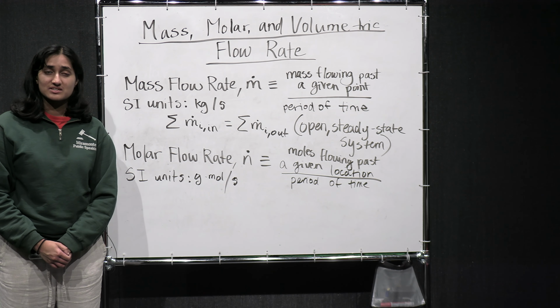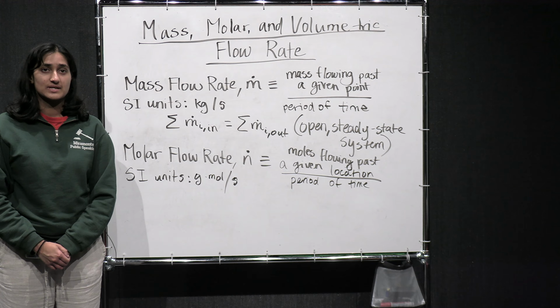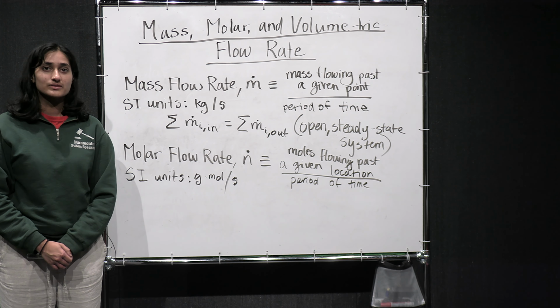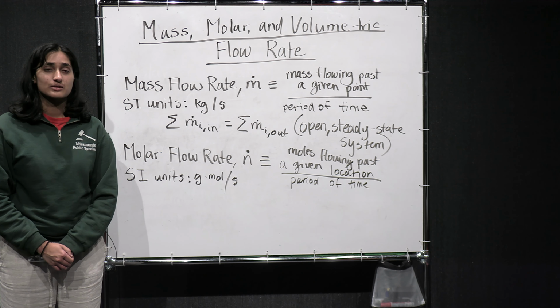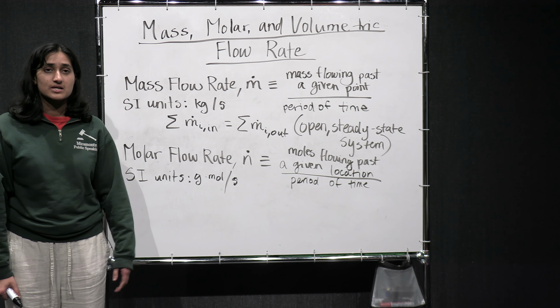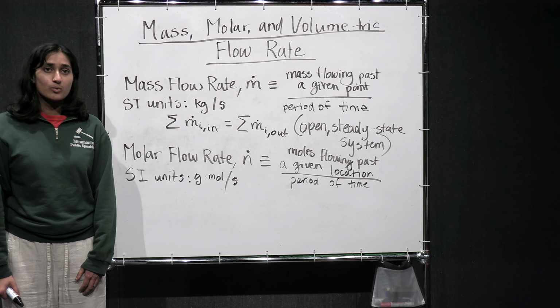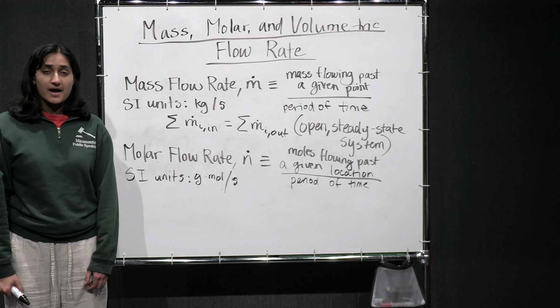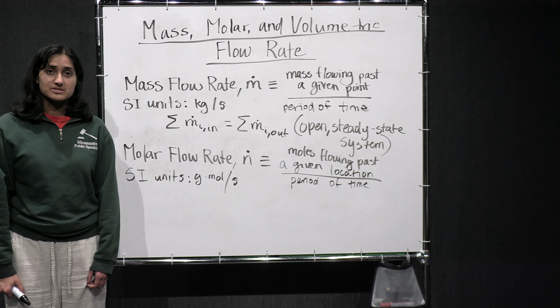For reacting systems, it is generally not true that the moles in equals the moles out. Several later videos will deal with the molar flow rates in reacting systems. For open, steady-state systems with no reactions, the equation form is the sum of the molar flow rates of species I in has to equal the sum of the molar flow rates of species I out.